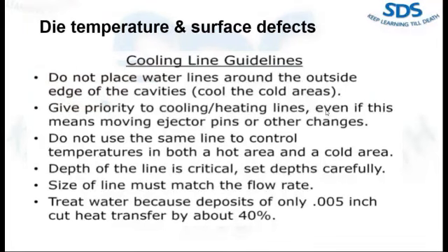First, do not place water lines around the outside edge of the cavity. These areas are already cooled, so we don't need to keep the water line outside the edge of the cavity. Second, when designing the die, give priority to cooling and heating lines even if it requires moving ejector pins or other components. Do not use the same line to control temperature in both a hot area and a cooler area.